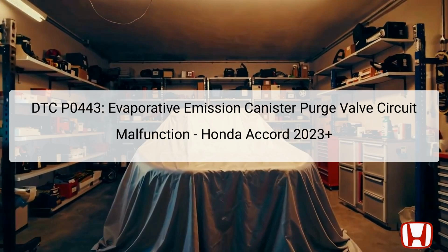Welcome to the detailed troubleshooting guide for DTC P0443, labeled as the Evaporative Emission Canister Purge Valve Circuit Malfunction for the Honda Accord 2023 and newer models. This diagnostic trouble code, DTC, signifies that there is an issue with the monitoring signals related to the Evap Canister Purge Valve. The electronic control unit, known as the PCM, Powertrain Control Module, has detected that the return signal from the valve does not align with its expected outputs. Consequently, the PCM records this abnormality and triggers the code.